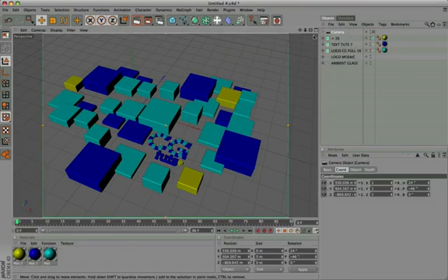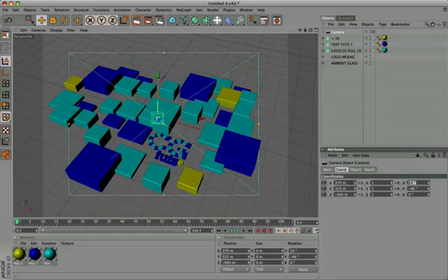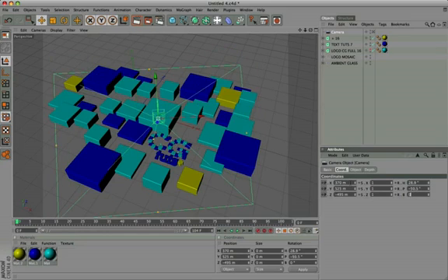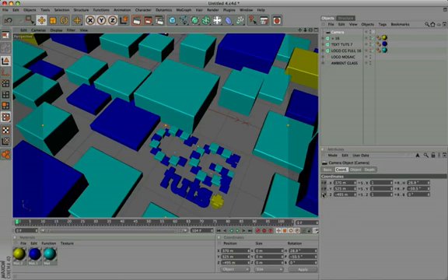We insert the camera, and extend the timeline from 90 to 104 frames. In the coordinates panel, insert the following values: x 370, y 525, z minus 495, h 28.9 degrees, p rotation minus 50.5 degrees, b 0. Activate the view from the camera, by Cameras, Scene Cameras, Camera.